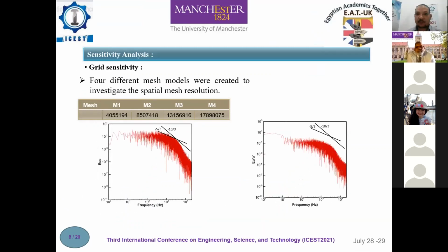An additional assessment of the grid quality can be carried out by inspecting the power spectral density of the instantaneous streamwise velocity and velocity fluctuation, calculated based on a time series consisting of 72,000 samples. The -5/3 slope of the spectrum in this figure confirms the suitability of the grid for the current LES, indicating that the implicit filter for LES lies within the inertial subrange close to the eddy dissipation region, which is one of the basic demands for well-resolved LES calculations.